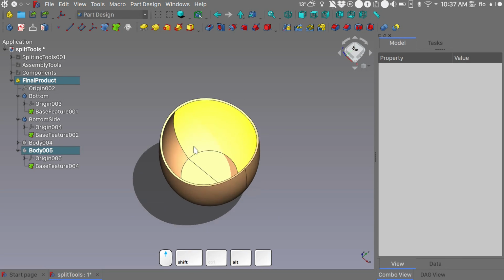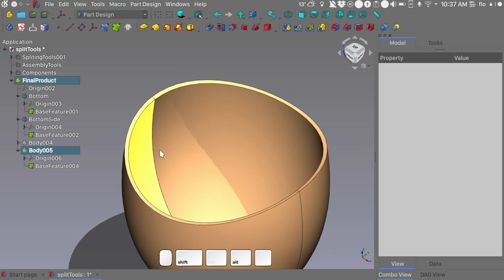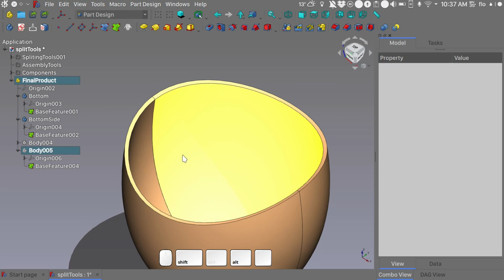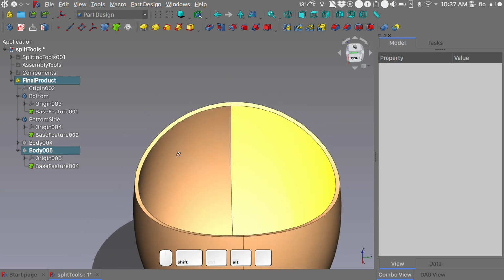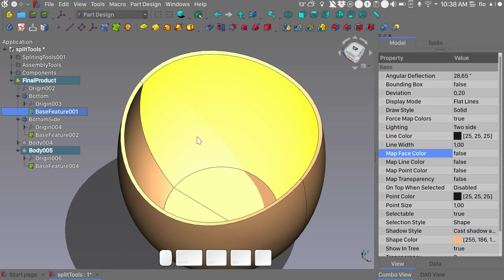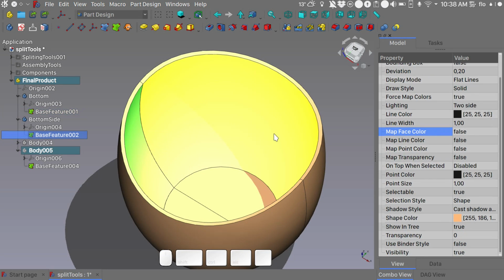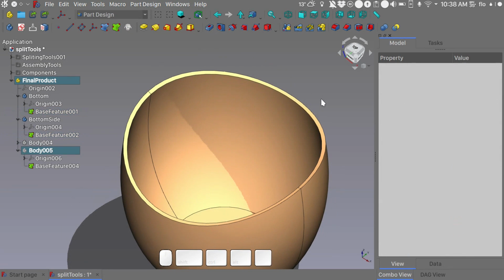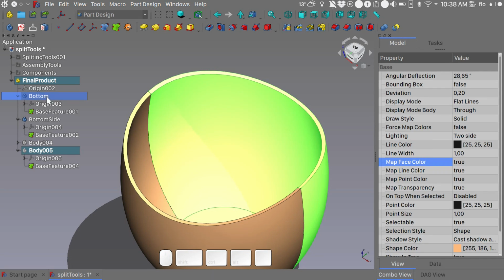What I want to do is to create some kind of connection between our two pieces that closely follows the interior contour of our vase. To do this, we will once again use the Boolean tools, and let's concentrate first on the bottom body.